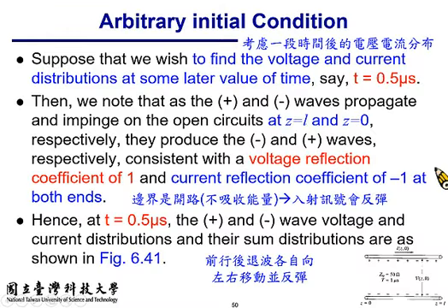However, since we already decomposed the total voltage in terms of V plus, V minus, I plus, I minus, we can continue our analysis with this specific time delay, that is 0.5 microsecond. And as I already mentioned, because the terminations are open circuit, which absorb no energy, all the incident signal gets reflected, and the reflection coefficients at the two ends are positive 1 for the voltage signal and negative 1 for the current signal. So remember to reverse the signal, all right?